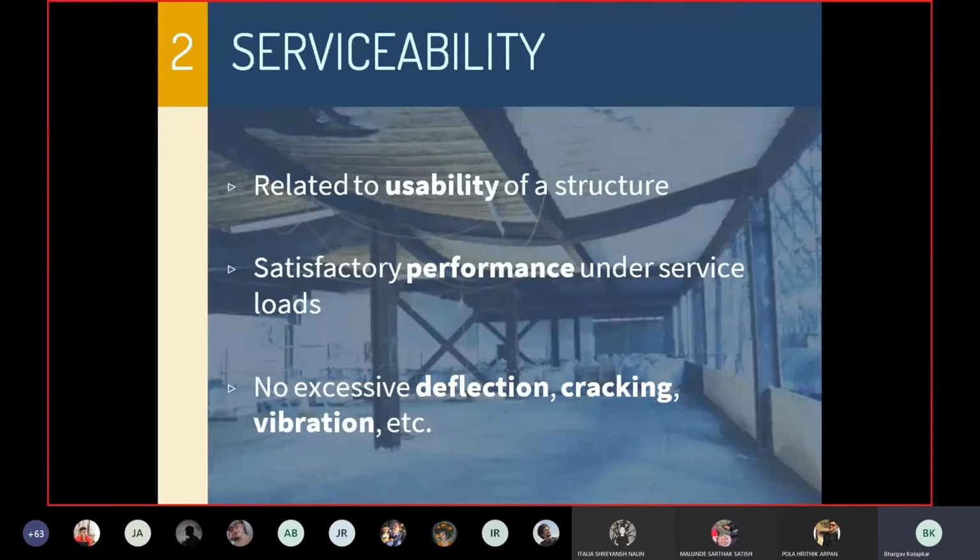So what was exactly happening? The portion of the bridge that resists wind is the deck. If it is a solid belt, then the entire belt is resisting wind from flowing, and because the wind is stopped, it would have to go above and below the deck. It creates turbulence, and because of that the deck started swinging. Had it been an open structure wherein the deck would not act as a solid belt, but say a perforated one, then a majority of wind would pass without exerting a lot of pressure on the deck. That is the reason why the deck started swinging. Now this is different from a structure having its own time period. The time period is a function of how stiff the structure is, so that is a little different from this phenomenon of resisting wind.